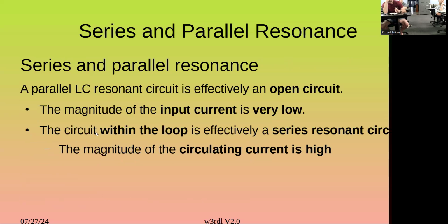Okay, kind of talk about all this stuff. When you're actually at resonance in the parallel LC circuit, we tend to call those tank circuits. The input current, because it looks like a high impedance, is going to be very low. That's going to be whatever the resistive value is.